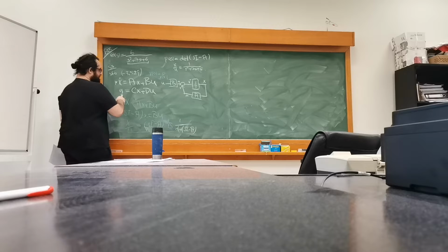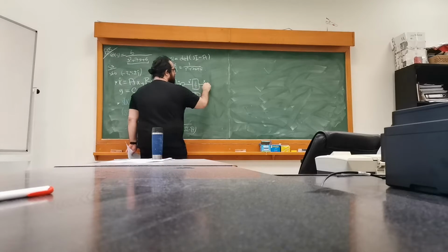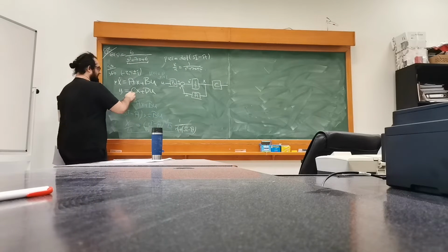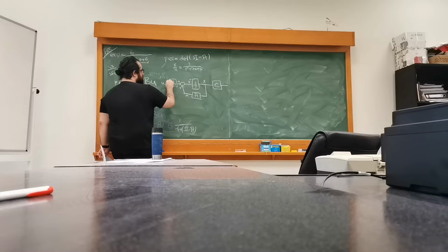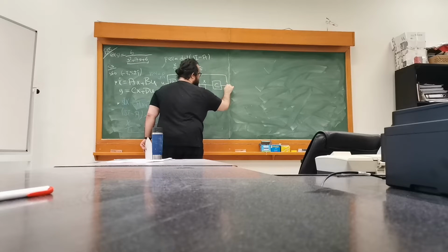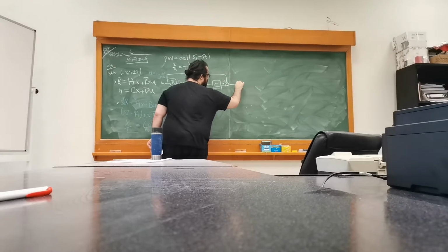And therefore I will use this here. Since I have this x vector, I can combine it with C here. So taking C times that will give me Cx. Since I have u, I can multiply that with D and add it to the output. That gives me y.